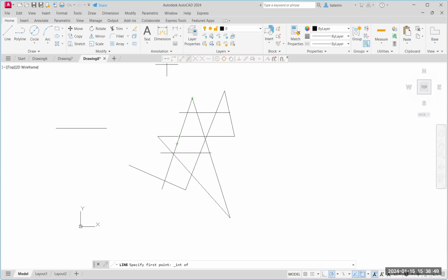It's a one-time click. So if I click my intersection here, now if I go back, notice the midpoints are coming up, endpoints would come up, intersections would come up. So just keep that in mind. All right, so today we covered how to do absolute, relative, polar, and direct dimensions. We learned how to add this menu up here and how to create this quick, short object snap toolbar.